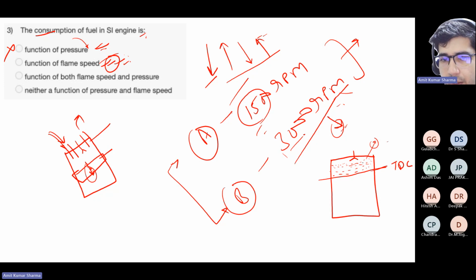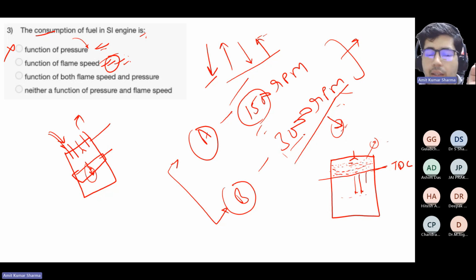It reached here and it will go down. So if you are having very low RPM, then what will happen? Maybe your spark is sufficient to ignite up to this, and then the stroke has already started, and maybe the last fuel front was not ignited at the particular time. Your expansion stroke is already on, your piston is coming down, and maybe the temperature is not sufficient, or for any reason, maybe the whole fuel is not burnt.